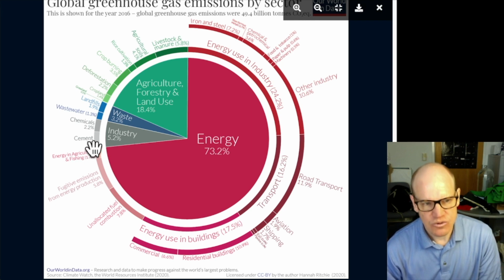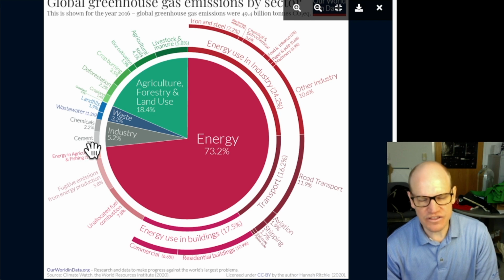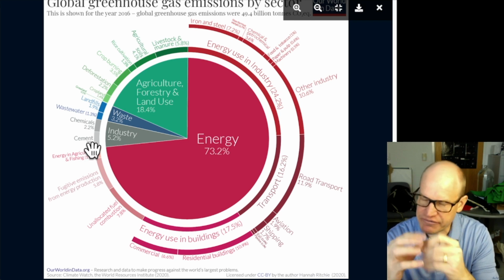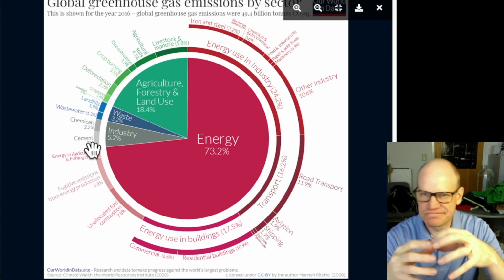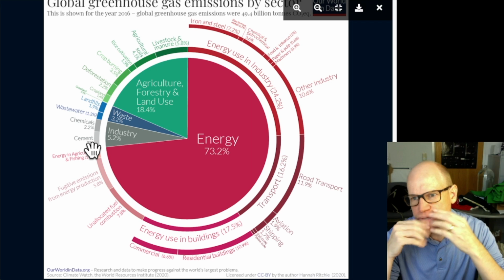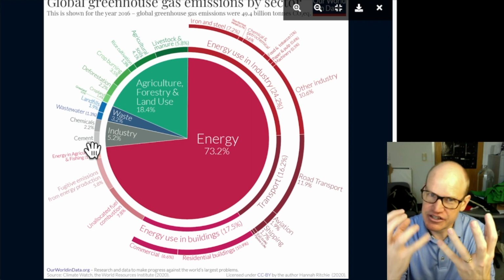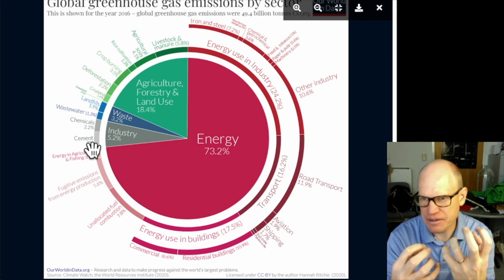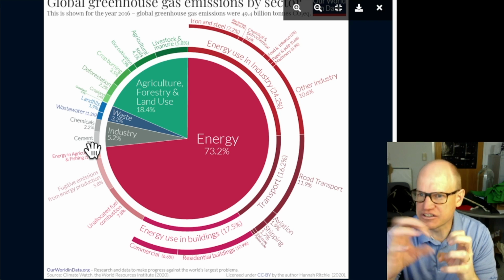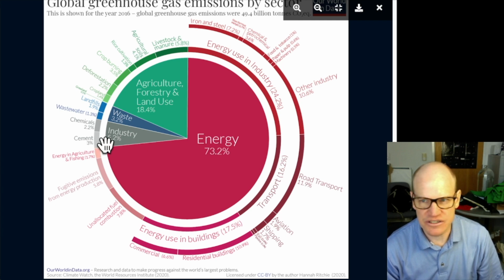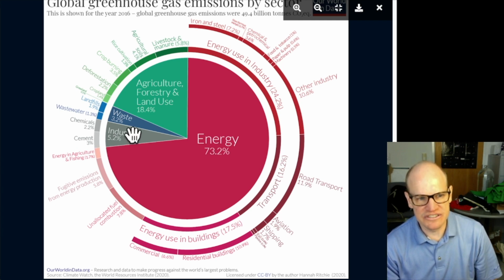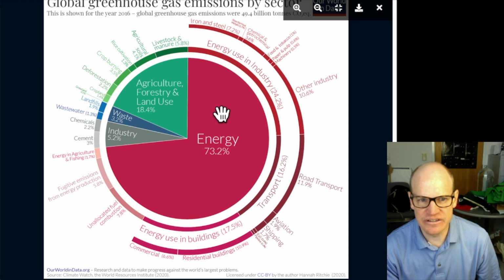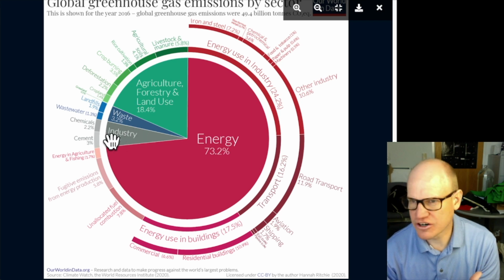So cement here, when you make cement, you have to reform the limestone. You have to reform the chemical bonds in the limestone into some other thing. So there's two different chemical things that you transform from one form into another under high temperature, but that transformation releases carbon dioxide that came from that process itself. And so that's what this industrial waste comes from. So there's actually parts of cement production that are in the energy side of this thing that are different from the industry side. So this is stuff that there's no way to control this carbon emission